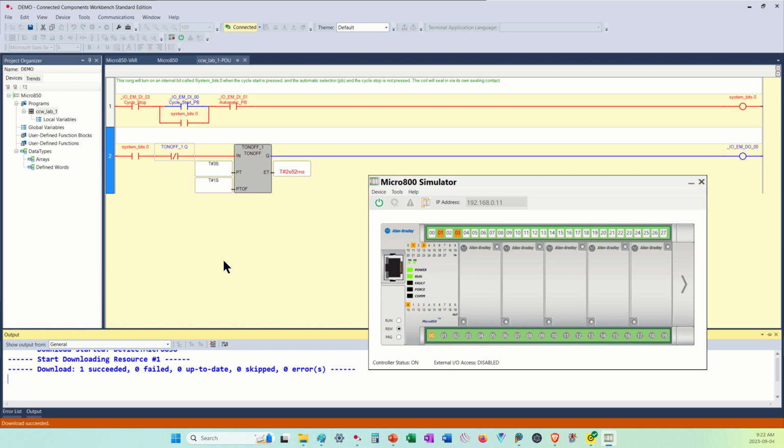I can adjust that. So if you're using a common horn or you're using a common light, this is a lot easier to work with, and it allows you to say, okay, under this condition, I want a long horn with a short beat, I want another long horn with a short beat, and that pattern, everybody in the plant will know it's a fire, or everybody in the plant knows that this machine's starting up, or it's a particular sound that's distinctive.